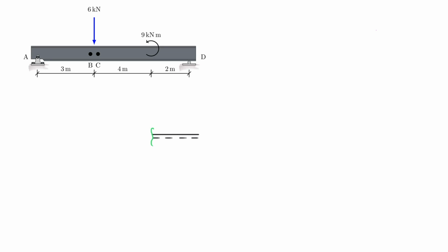And my support reaction now actually has a value of 1 kilonewton here. And I will bring in my card, the other side of the card now that I flipped into half, and you will find that the moment goes in this direction, shear force in this direction, and the normal force in that direction. And this now would be, of course, at location 7 meters to the right.